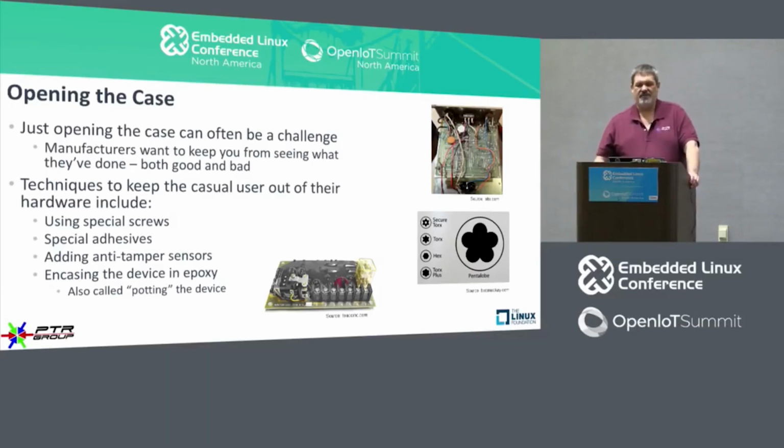And they do that for several different reasons. One of them is to keep you from figuring out what the circuit is. Other times it's to keep it from getting wet. If it is going to be in a moist environment, we'll want to keep the circuitry dry, so they'll do an epoxy coat like this. Or if you happen to be going into space, it's called conformal coating, and it'll keep your devices from outgassing.